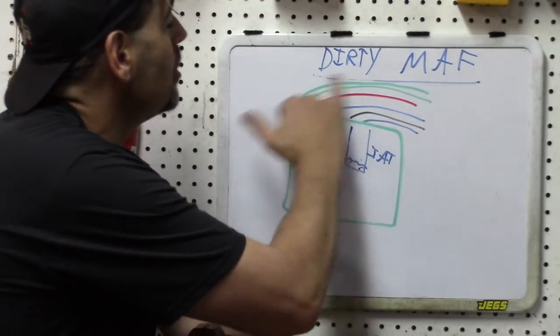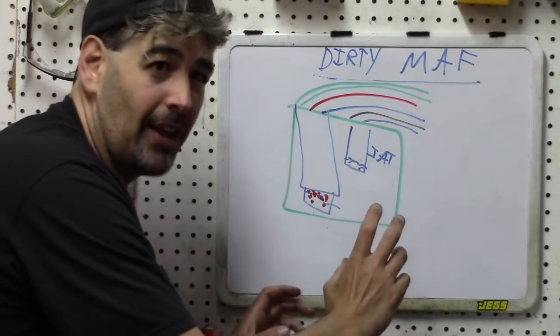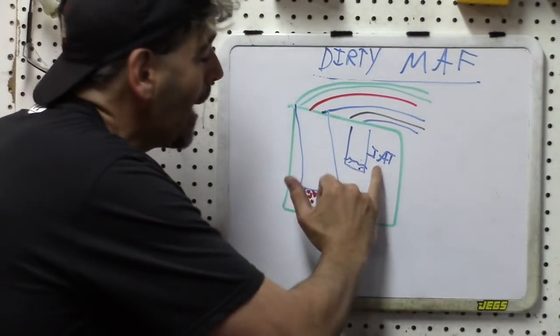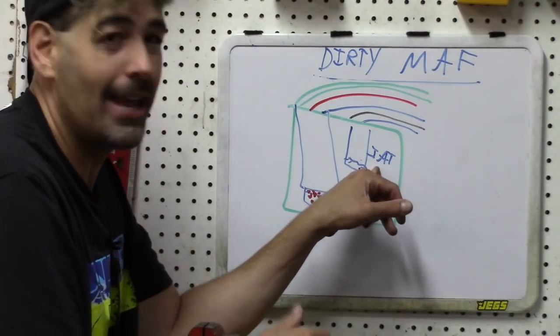So again, knowing your components, I would have paid much more special attention and asked myself, am I really cleaning the mass airflow sensor? How do I know that I'm not just cleaning the IAT?